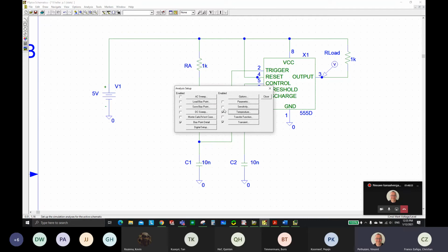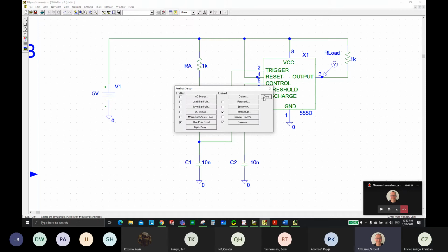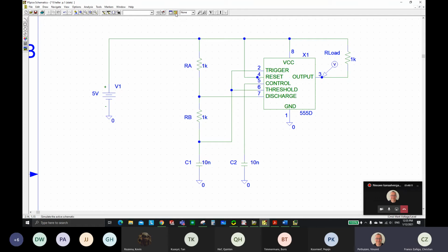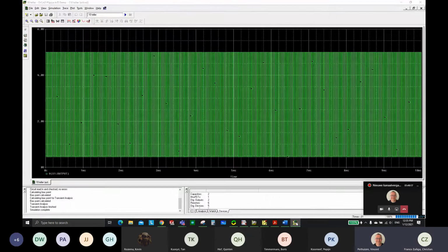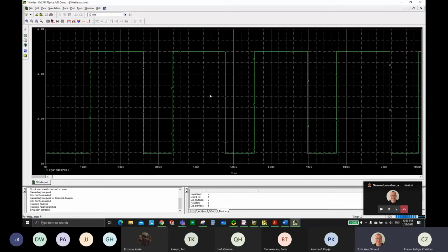Click OK and run the simulation again. No, you clicked the cross. Don't do that. Please go back. Always click the close button, but check, is the temperature at 50? Run the simulation again. I remember the values you had, 69 and 48. If you set these values in your transient value, you don't have to change the value in the probe each time, but it's okay. Do you still have 68 and 49?